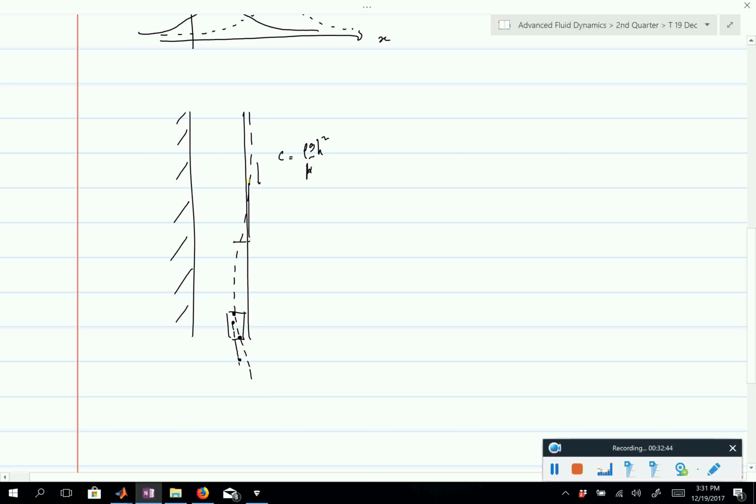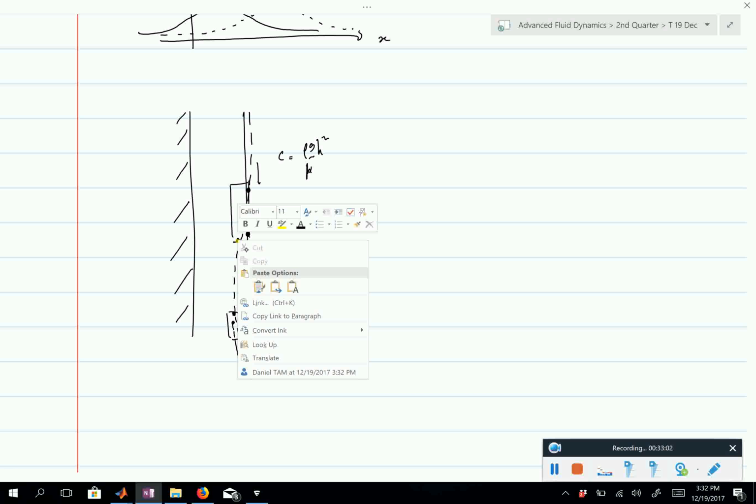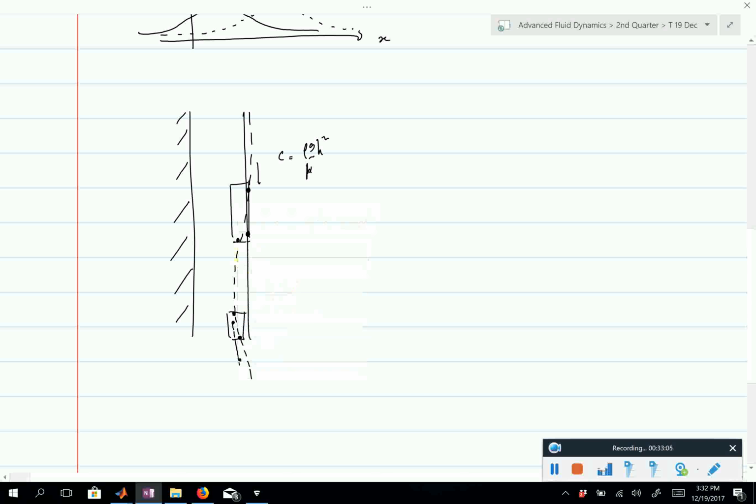That's okay. The problem arises here. If I look at this little piece, note that right here the thickness is larger, so the velocity is faster. So maybe it moved here, and right here the thickness is smaller, so the velocity is slower, so maybe it will have displaced here. So that piece which was initially relatively flat now becomes much sharper.